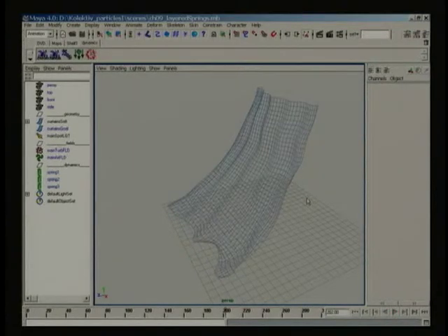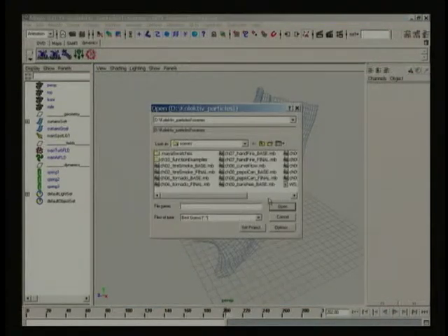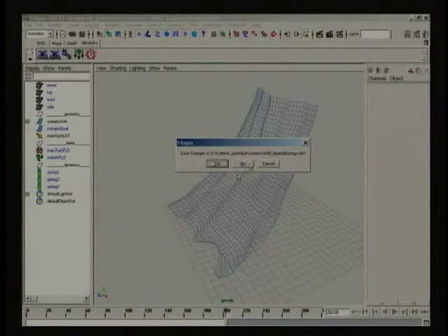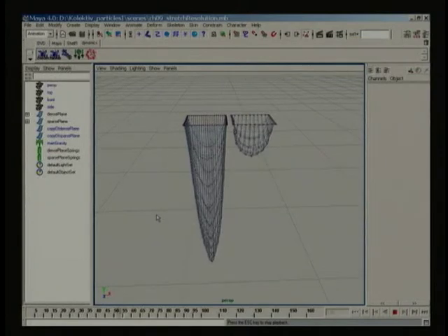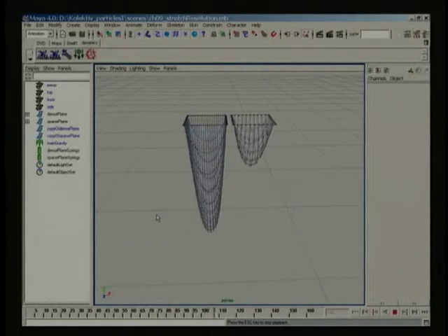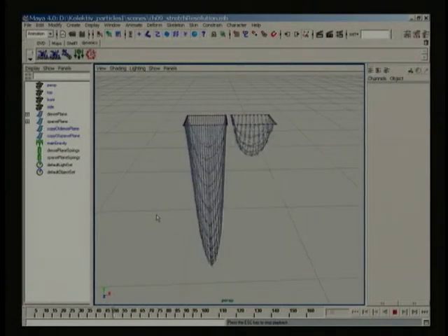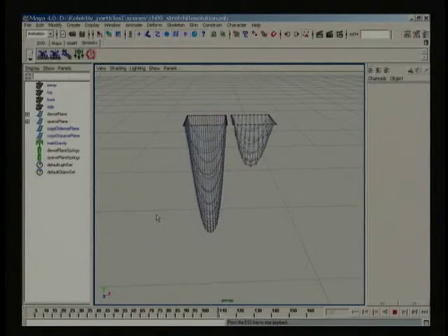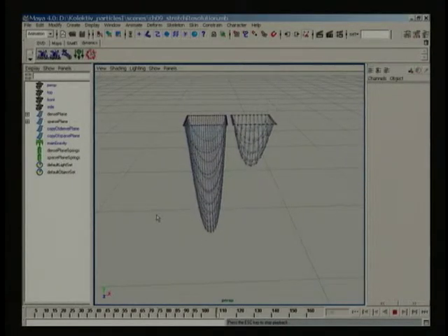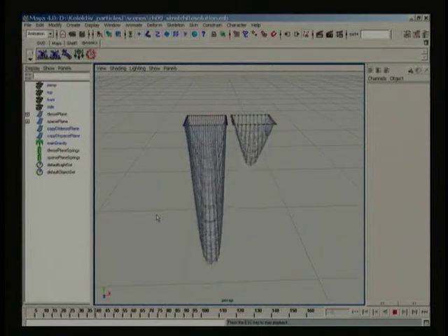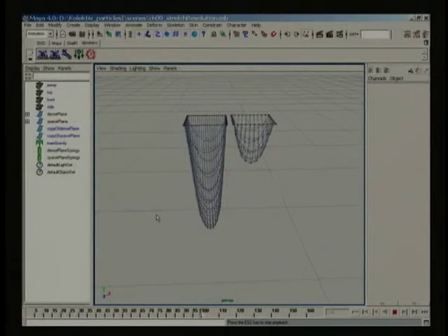This file, called ch9 stretch resolution, demonstrates how different geometry resolutions will give different results. Here I have two planes, both made into softbodies with the outer row of CVs set to a goal weight of 1 and the rest set to a goal weight of 0. Both planes have springs created with a walk length of 2, which have identical stiffness and damping. The same gravity field is applied to both grids. The grid with 4x4 spans stretches 25% less than the grid with 8x8 spans.